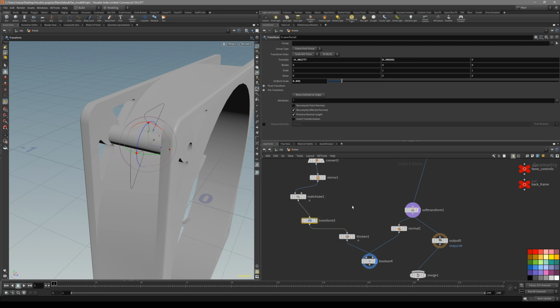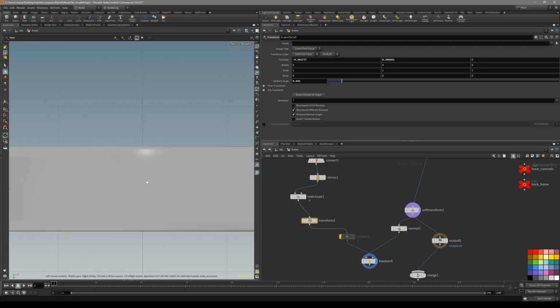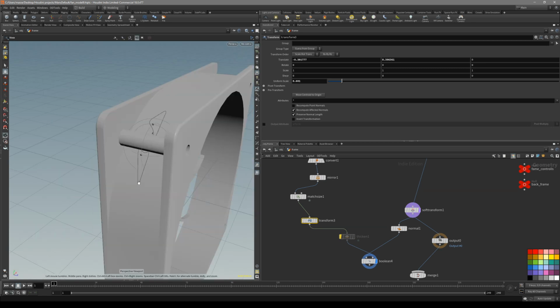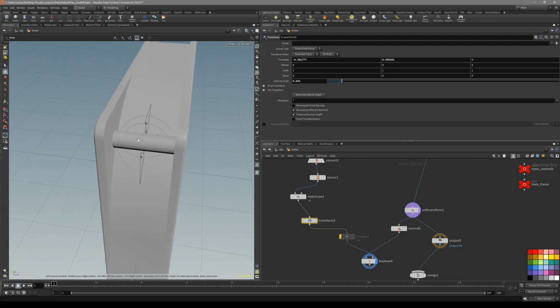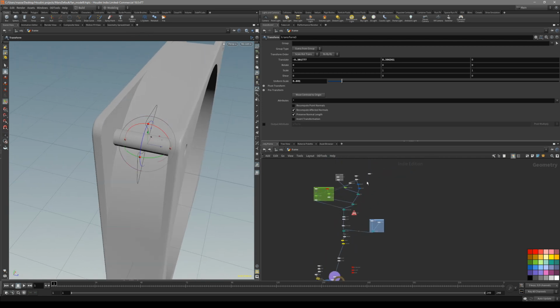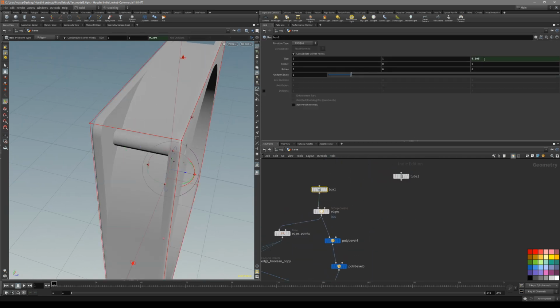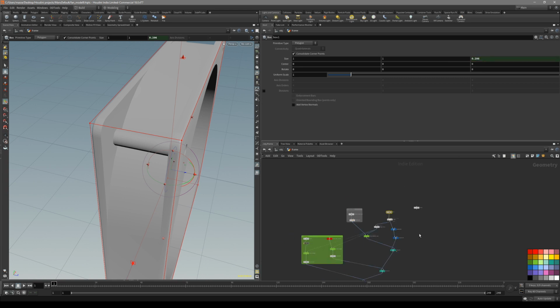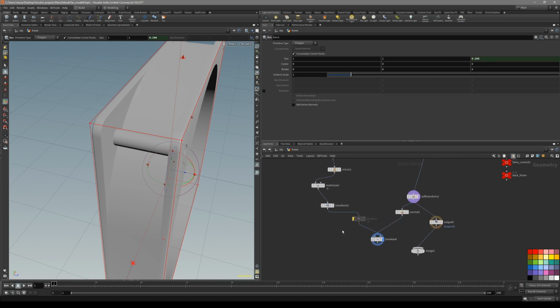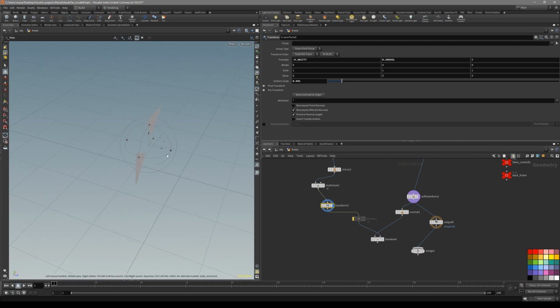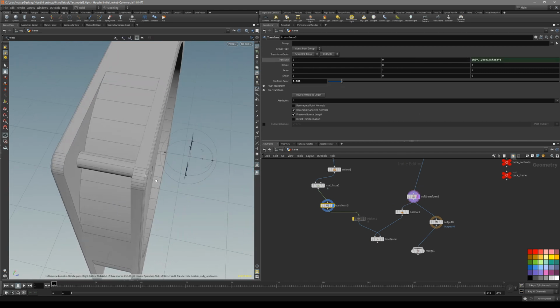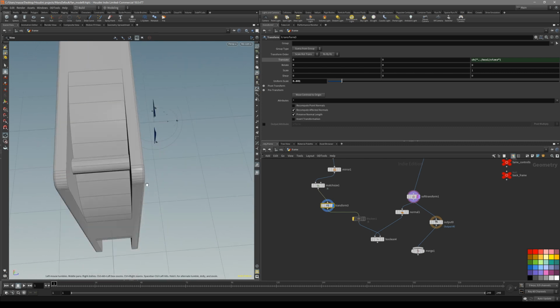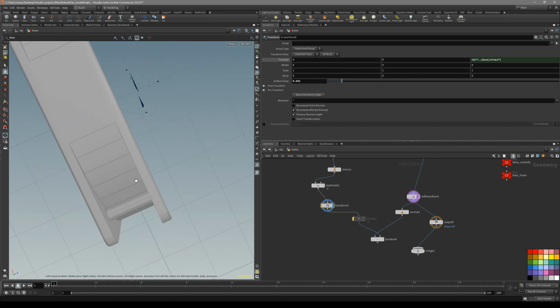If you disable the thicken, if you think about it, this transform is now at the very center of the world. And we do know how thick our box is. So what I'm going to do is go back to the top and copy the box amount, go back in here, in transform, and in the Z, paste it inside. Now what we have done is moved it in the Z direction the exact amount of this box.